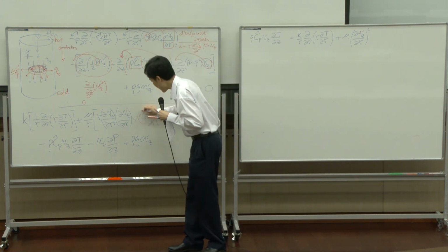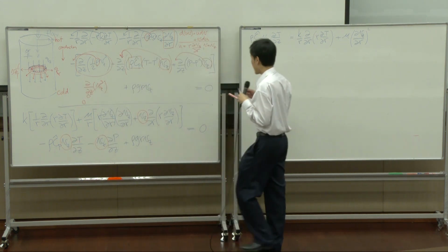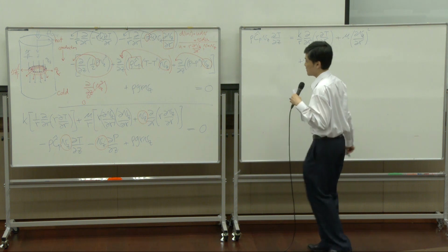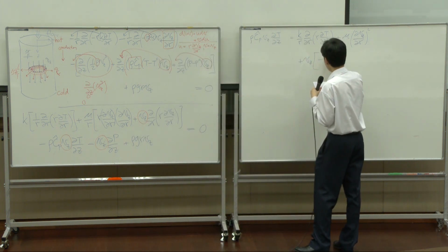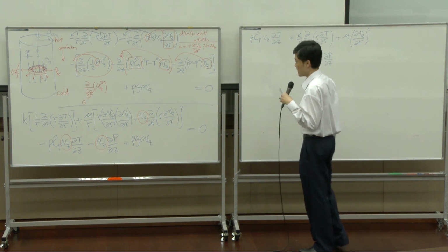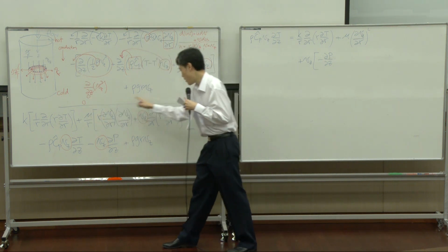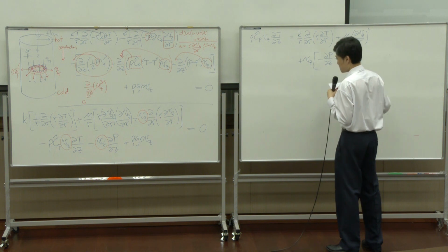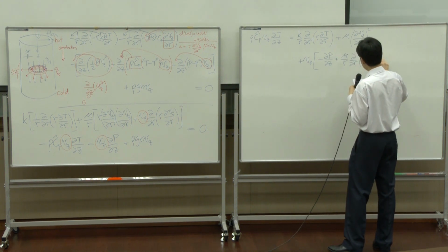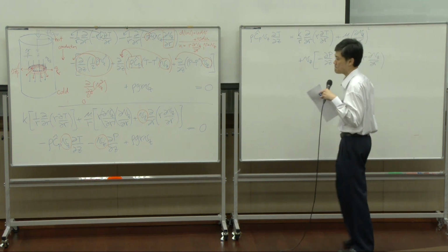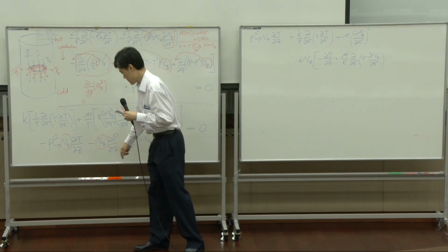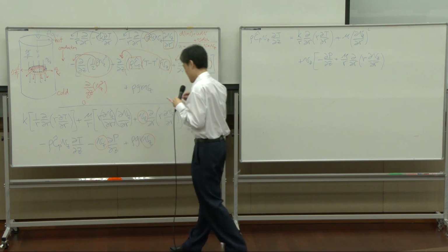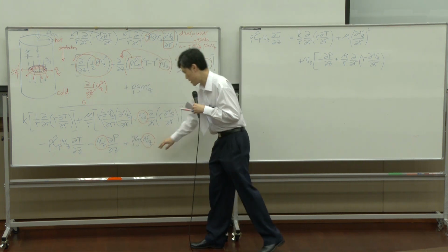Then the next three terms, I have Vz, Vz, Vz as a common term. So if I take Vz out, inside, let me write down this pressure term first. I have dP by dz. And then this term, taking this mu and R inside, I have mu over R d by dr R dvz by dr. Okay? And the last term, oh, I'm sorry. This term was already taken care of. This must be incorporated. These three terms combined. So the last term will be this term.